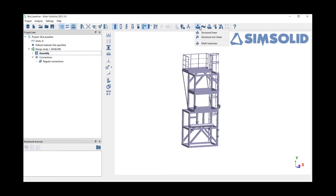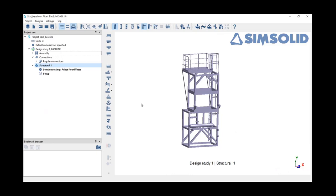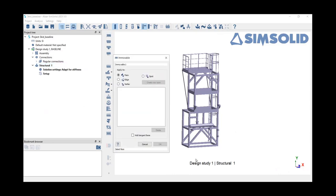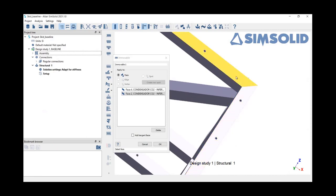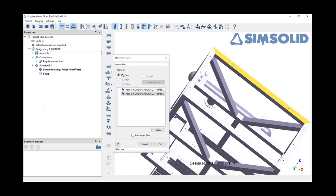We'll talk about some of the different analysis types that are supported in SimSolid, but for starters, we will just set up a basic linear static analysis. I'm going to set up and constrain the bases in all the degrees of freedom.